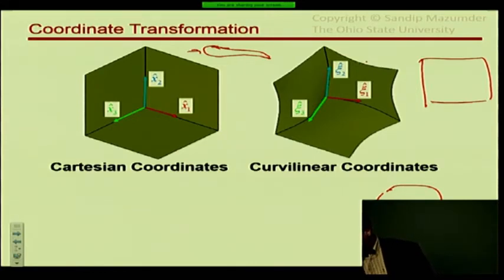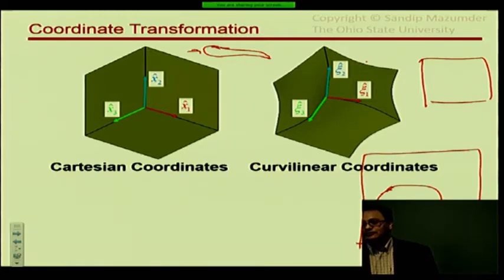You have, let's say, a circle inside a square. Now, how are we going to model this? What they would do is basically a staggered step mesh, sort of approximating the outline of the circle. I'm not doing a good job here, but let's say you have a curve like that. That would be approximated by a stair step like that, which was great for heat transfer applications.